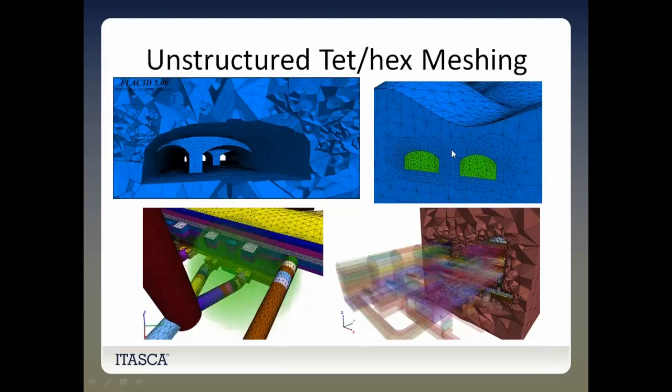So these hexahedra are really ugly hexahedra for most finite element applications, but for FLAG3D, which is really some sort of a finite volume, we call it finite difference, we don't have a very good name for it, but for FLAG3D, they are really not a problem. The valence of some points is very high, while at other points the valences are lower. Surfaces are often very warped, but again, since FLAG3D will subdivide these things into tetrahedra, those do not necessarily come in. So we have been quite successful in generating meshes by this method.